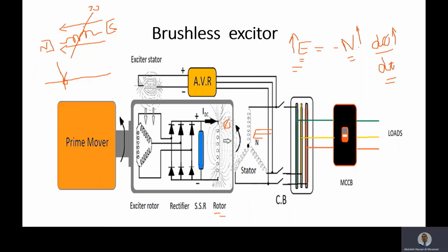If you increase the angle like this, more flux lines will be intersecting and more voltage will be produced in the coil, okay. The maximum flux value which will be intersecting the coil is at 90 degrees. So at 90 degrees here, you will have the maximum voltage produced in the coil.